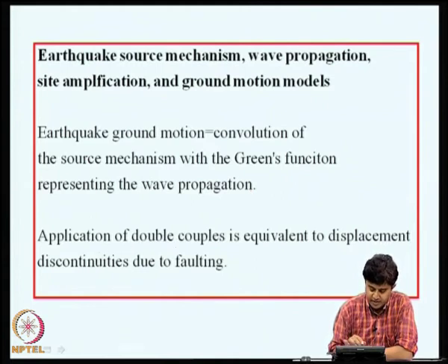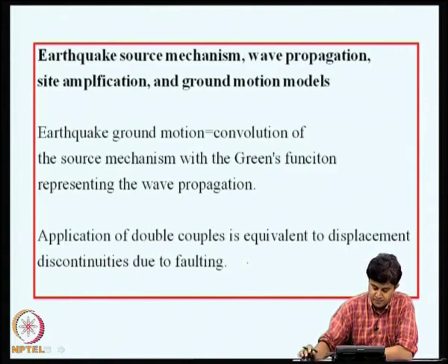Now, application of double couples is equivalent to displacement discontinuities due to faulting. This is one of the models that is often used. The relative displacement along the fault is replaced by action of double couples, and based on that Green's functions are derived.